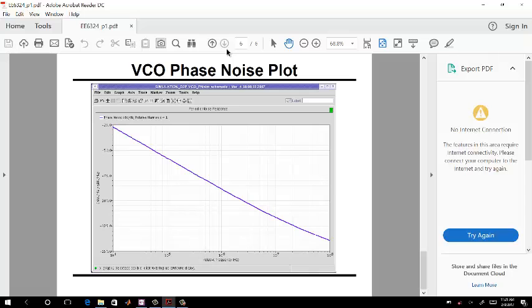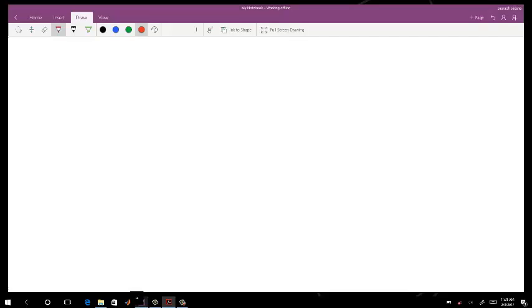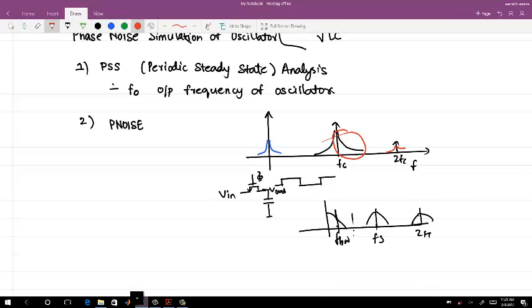Okay, and the other easy part will be that once you find the phase noise, you know the relation that if I double the power, my phase noise will reduce by 3 dB. Those things you will find when you actually design an oscillator. So if I find, let's say for 1 milliwatt, I get minus 90 dBc at 1 megahertz of whatever noise profile I got, and I do not get enough jitter, then I have to increase the power to reduce the noise.